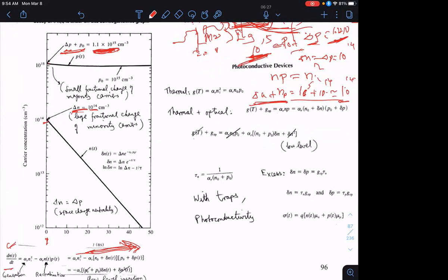So where you write it down is I look for the number of minority carriers as a function of time, dn/dt. So I'm writing n, the minority carrier electron concentration, as a time-dependent part, okay? And I can write that as the difference of a generation rate minus the recombination rate, okay?